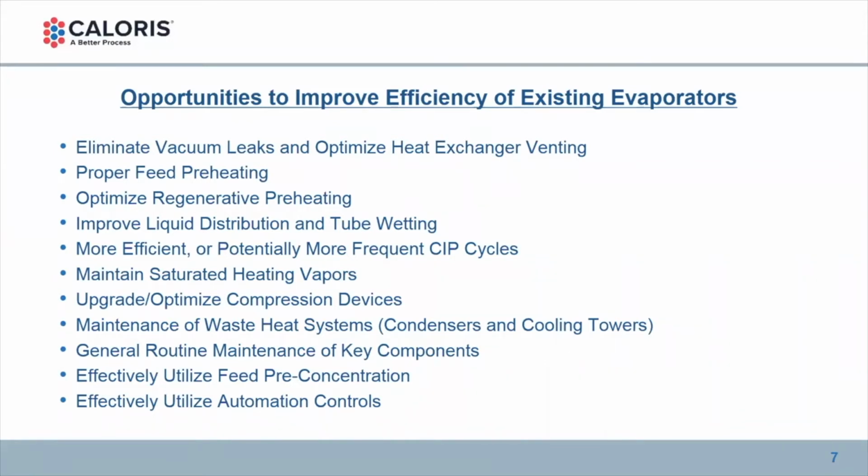If fouling is causing you to consume more energy, there's a certain point of trade-off where you're better off stopping, cleaning, and getting back online and being more energy efficient, rather than pushing the evaporator for an extended number of hours and just shoving more energy into it to keep it running.